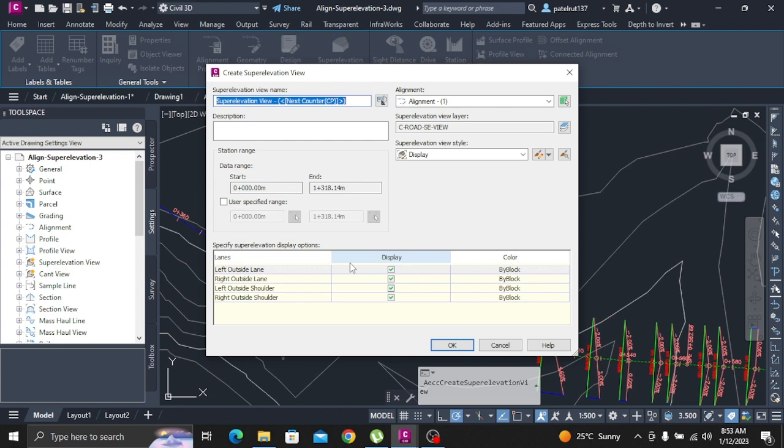Near station 0+900.00, Control plus click the green shoulder text. Only the grips of the selected superelevation region are displayed. Hover the cursor over the grip at station 0+908.44. The cursor snaps to the grip, and a menu of options is displayed. You can use this grip to either change the station value, or add or remove a critical station. Select Move End Normal Shoulder.